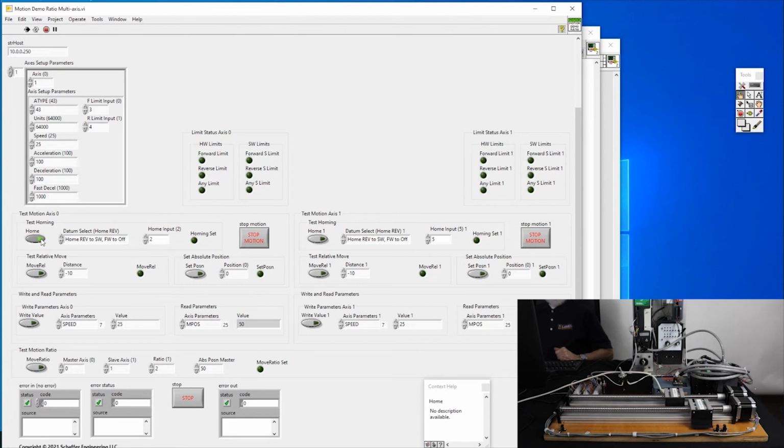And we can actually take that and we can change the speed. So in that last example, your master axis basically just ran 2 times faster. That is right. So we can then actually take the master and switch them around. Let's run the axis 1 as our master and axis 2 is our slave.